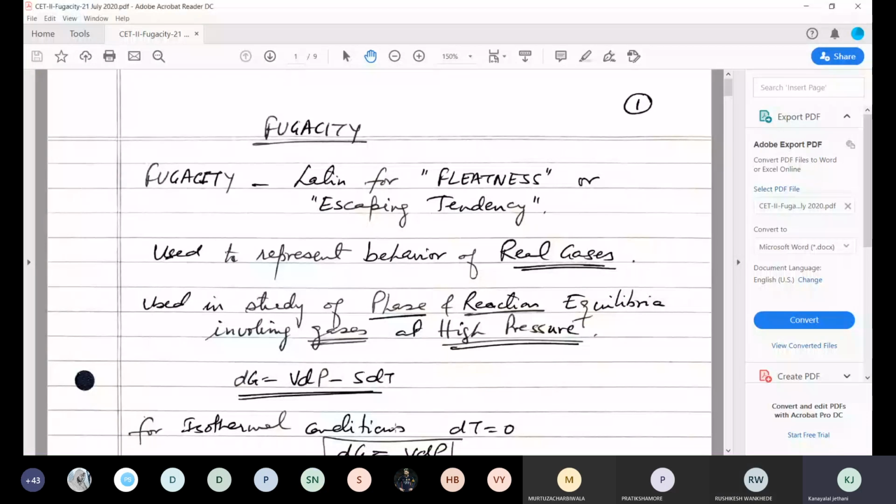The main thing I think we should think about is: what did he say at the start? He gave an example of two phases in equilibrium, right? Concentration was more in the liquid phase, concentration was less in the vapor phase. So individually we felt that the mass transfer should take place from the liquid phase to the vapor phase, right? Alpha and beta phase, right? But that was not the case because the vapor phase had more saturation, concentration at that temperature. That is why the mass transfer was taking place in the reverse direction. So just looking at the concentration, we cannot say in which direction the mass transfer will take place.